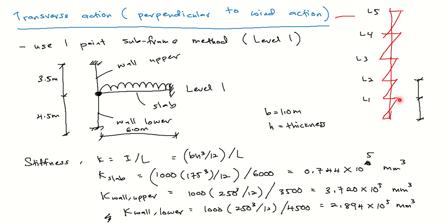We have calculated this one, 18.39 if I'm not mistaken, the value of the moment here, and this one is around 9 point something the moment, and we have designed the main reinforcement. Now we want to check whether we can extend the same reinforcement to the fifth floor here.